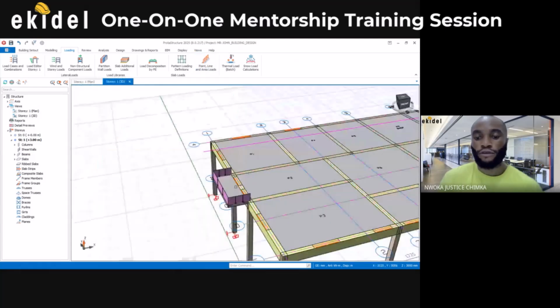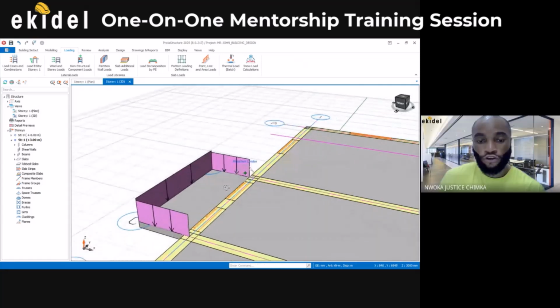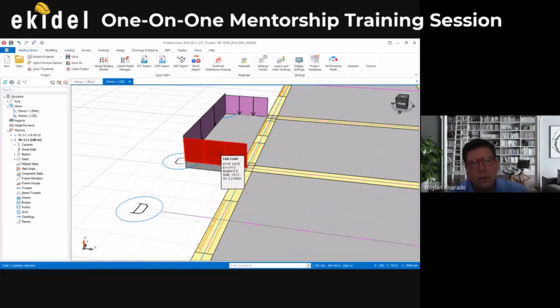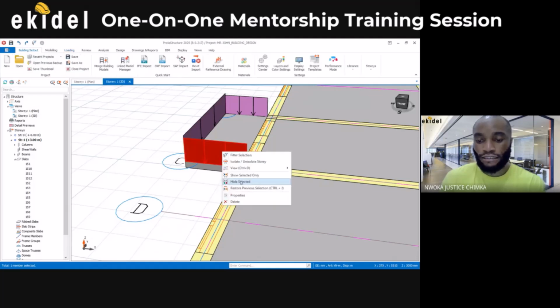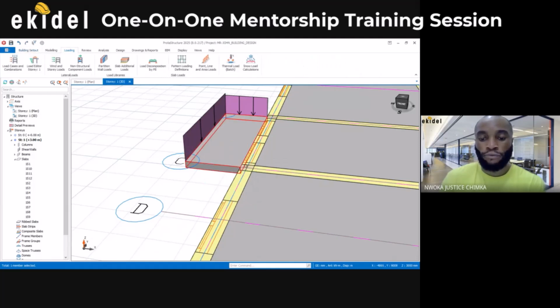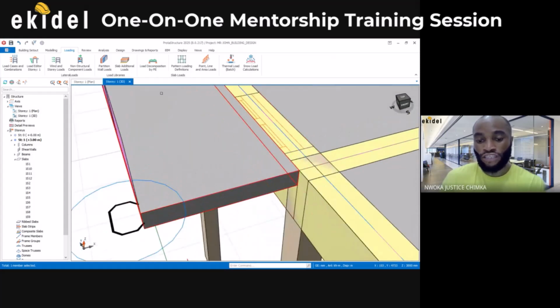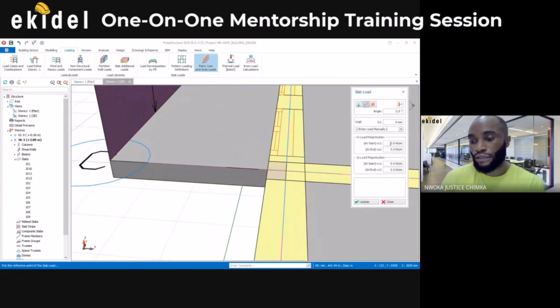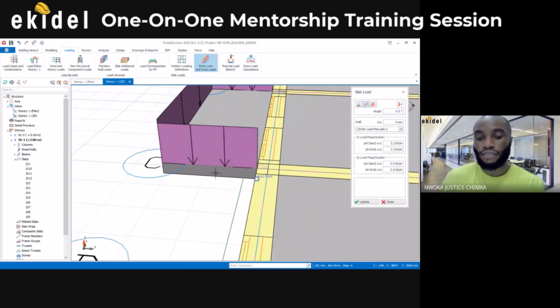And then how do you erase the one that was before? For example, what you do is first of all remove this one that's here before. Delete it. You just click on it, and then right click, and then you can see delete. Then come back and add a new load. I can see add load while I'm still on this view. So I'll click on the load, then line load, and then 3.2, which I want to use. Then locate this point, and then this other point, and add it. Can you see that? Yes.